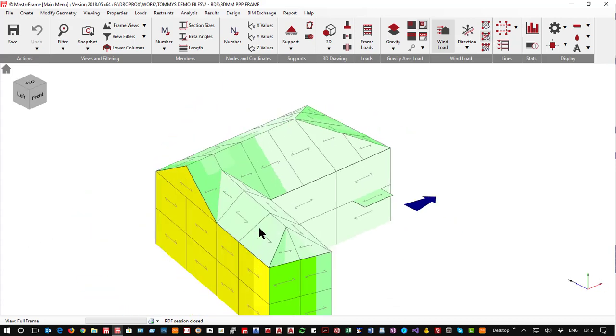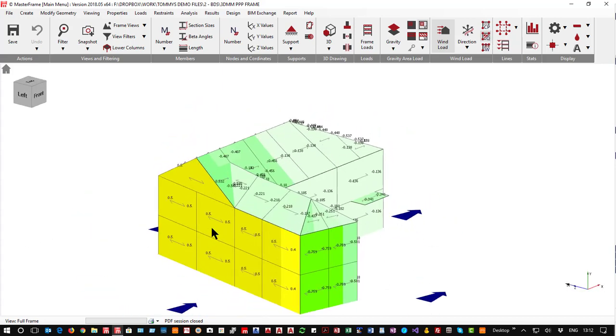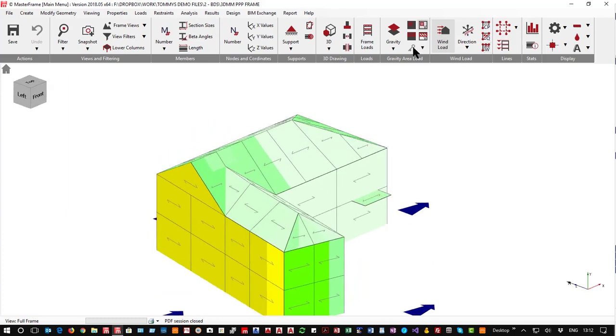And if I just rotate that around, you'll see that we're getting 0.5 here for wherever my location of building is in the world. So if I go back to CP, you'll see you get 0.7s and 0.8s and 0.9s, and then 1.1s on the leading edges. But when you times that by the external wind pressure, it goes down. And then you have, as before, your zones. So all very, very easy to work.